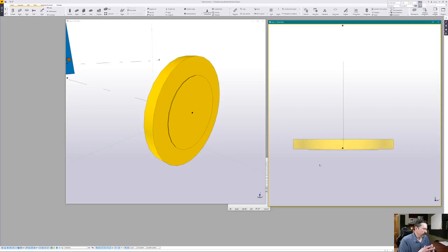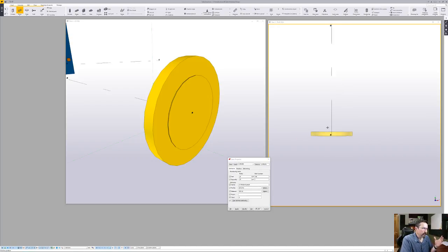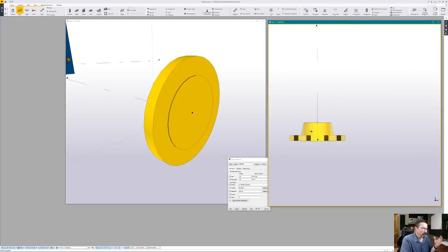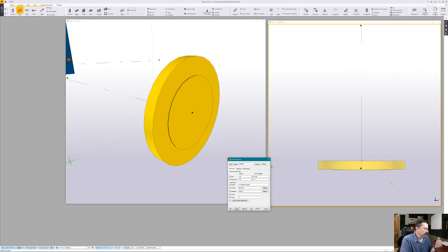And the weld neck for this is kind of a special profile. So I'm going to come in here to my beam properties again, and I haven't closed it yet. We're still using all the same properties. I'm going to come up to beam, and we'll get my beam started again. And this time for the profile, instead of using a diameter, because it's not an actual round piece, you can see it has a taper to it. So we want to show that taper, and with that I'm using a different entity, a different profile.